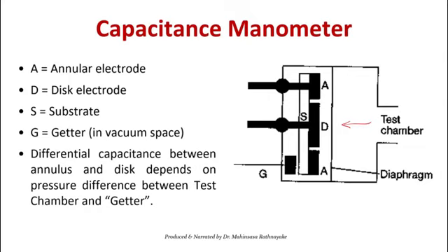If something displaces, the relationship between the displacement divided by the original length is called strain, right? So that strain or the displacement has a relationship with the resistance change, and that has a relationship with the voltage. So finally, from the electrodes or using resistors, you can measure a certain voltage, like you did in the thermometers, thermocouple thermometers, right? So finally, the measured value is voltage, but there is a relationship.